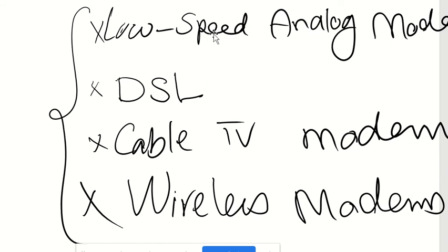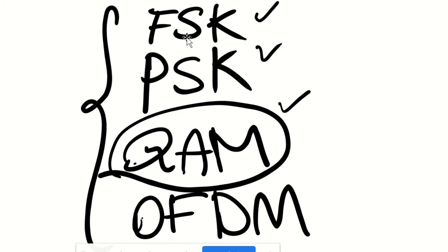Okay, now I talked about frequency shifting here. I started by talking about FSK signals, which, if you remember, I said typically occupy a wide bandwidth because of the sidebands that they create from the FM process. So several techniques have been developed to improve the spectral efficiency of FSK.